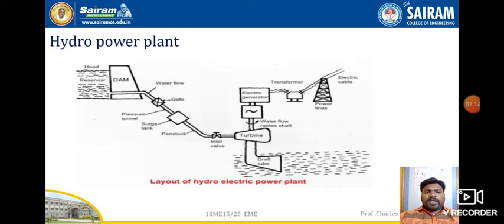So that is the working principle that we have seen. Once the water hits the turbine blades, the remaining water will be collected in the tail race with the help of draft tubes. You can see underneath the turbine blades there is a draft tube. When water hits, the turbine blades will rotate, and the remaining water will come to the draft tube, through which the water will be gathered, or settled, in a tail race. It is the place where the leftover water will be collected.